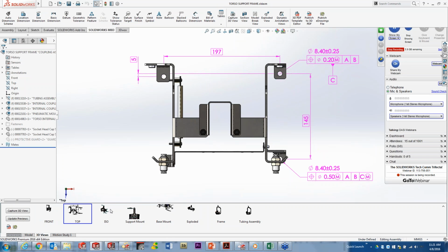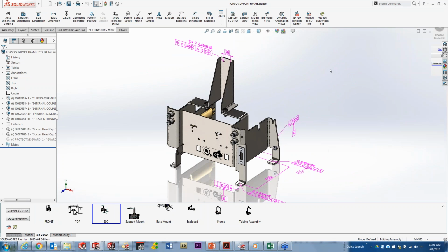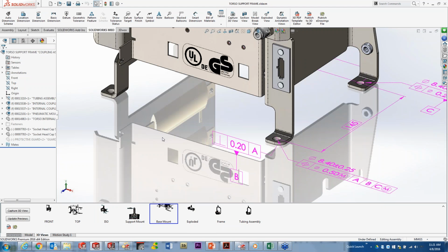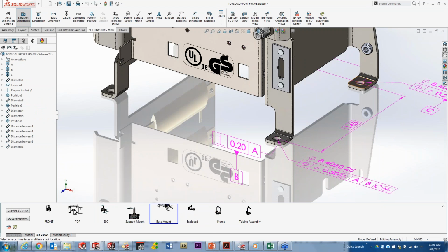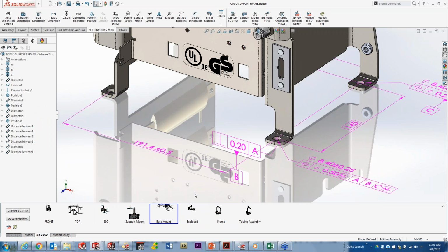Now over here on this assembly, in these orientations, many times what we need to do is dimension the stack up of how an assembly actually goes together. So in situations like this, we want to be able to apply these dimensions in the same way. So here we can simply grab holes, scheme this thing in 3D, and as we do that, it's going to apply a dimension in whatever orientation we snap our cursor. That dimension is now visible in all those 3D views and the main view here that we activated in order to create this.